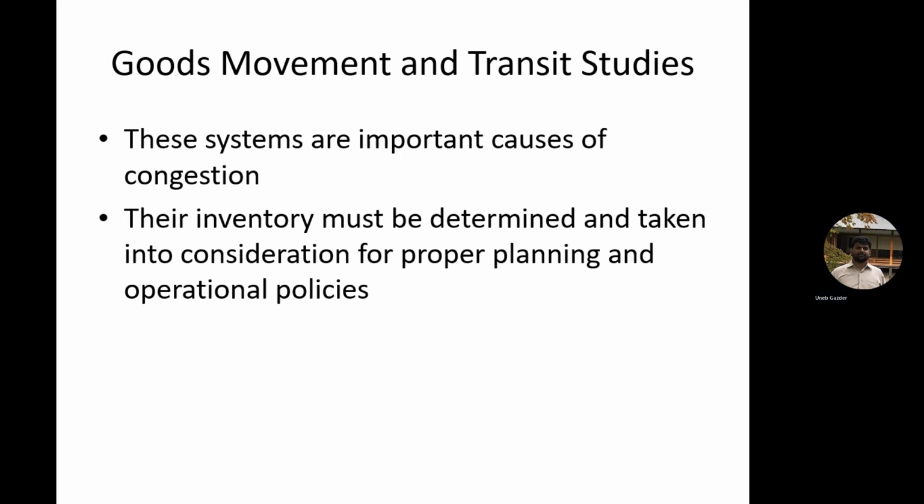Okay. These heavy vehicles can cause a lot of congestion, even if they are in small amount, because they are moving slowly. So they are slowing down everybody, and you have to keep more distance. They take more space to turn, and so on and so forth.